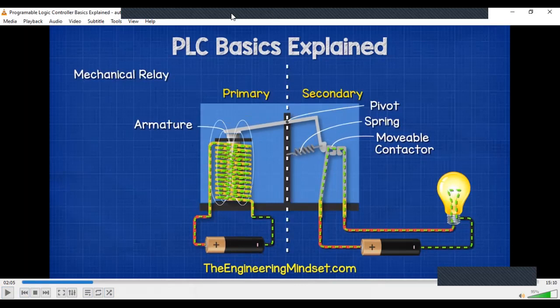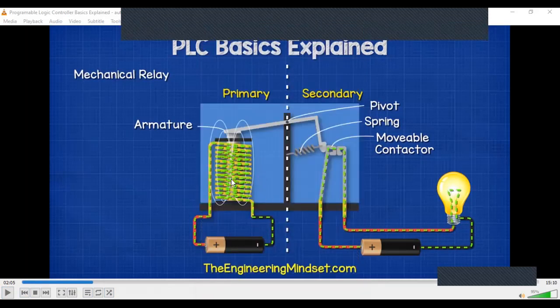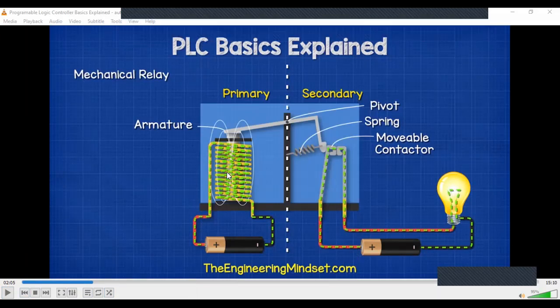You see how that, what is that? You see, based out of the actuation of this magnet, this arm is moving, isn't it? This armature is moving, and because of that you have a contact here. So there's basically some mechanical elements involved, isn't it? That's how relay used to function. It completes the circuit basically, right? Moving of that armature completes the circuit, and that's how it used to work.